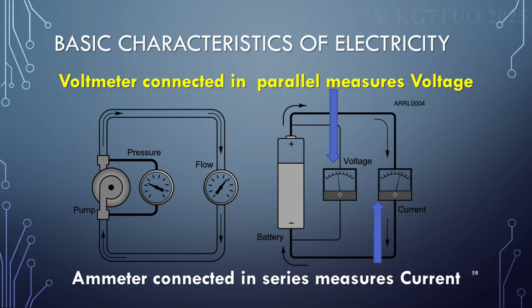What does it mean in parallel? Did we not cover that? Parallel is side by side. Series is in line with. I believe we cover it shortly. Yes, we do. There are 2 different ways to wire something. Remember the Christmas tree lights in the old days when you were a kid, and one bulb went out and the whole string died? They were wired in series. Oh, okay, now I get it. Because one open light bulb opened the whole circuit. So parallel just has the second wire to keep the flow to everything. Yes, we'll show you some drawings of it in a second.